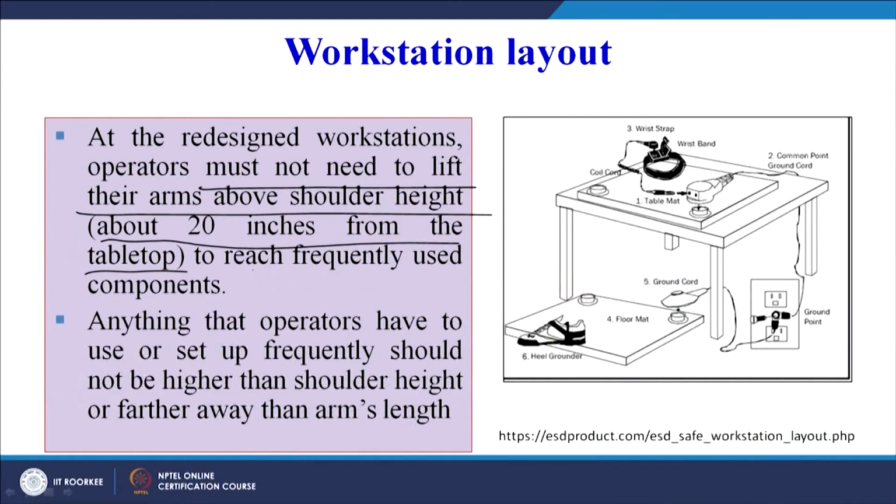So anything that operators have to use or set up frequently should not be higher than the shoulder height or farther away from the arm's length. Whatever is to be used frequently is the key word here. It should not be higher than the shoulder height, which is the same as the first point, or farther away from the arm's length. So it must not be too far away from the arm's length.